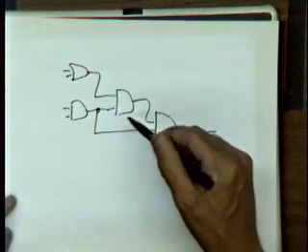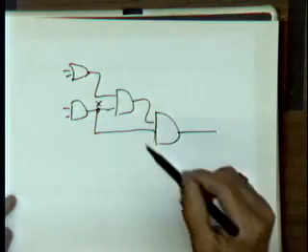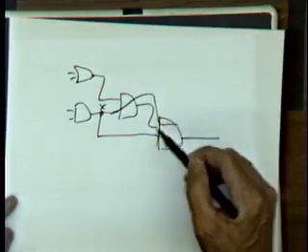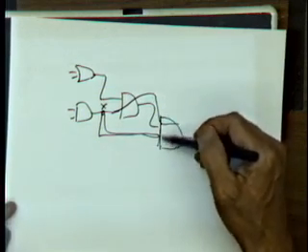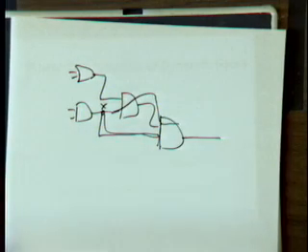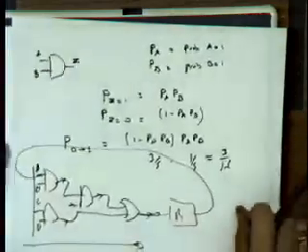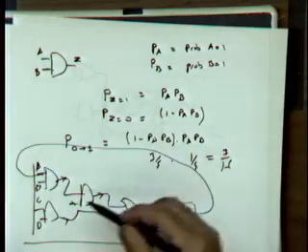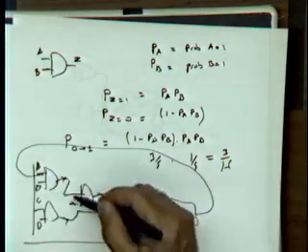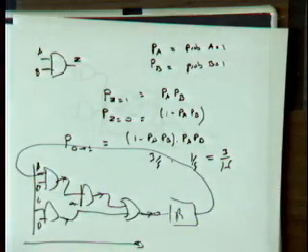If you look at this signal here, X, it propagates to here and through here. So both inputs of this AND gate are a function of X, indirectly. Now, this whole analysis I've done here assumes that all my signals are statistically non-correlated. I can only do this moving forward, assuming that all my probabilities are independent.